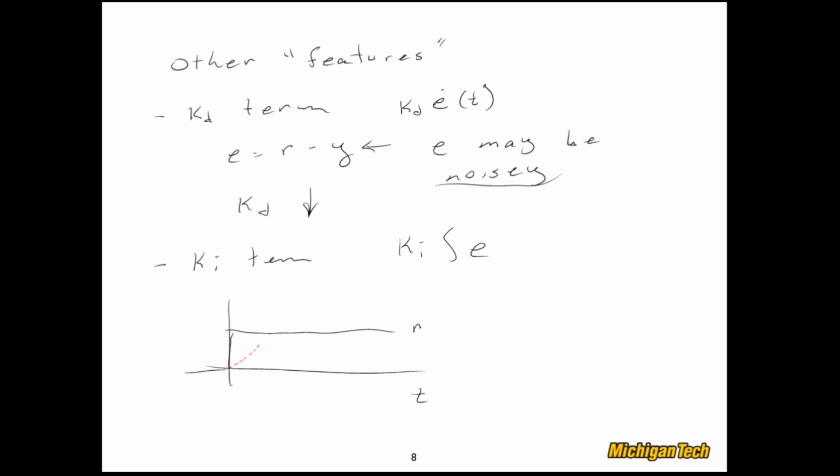Well, as it's doing that, a bunch of error is accumulating, and that error is being integrated and held onto. So that means that the response is going to have to overshoot in order to reduce that error, in order to get rid of this stored error that it integrated. And that's another way to think of why the integral term can give us that oscillatory behavior.